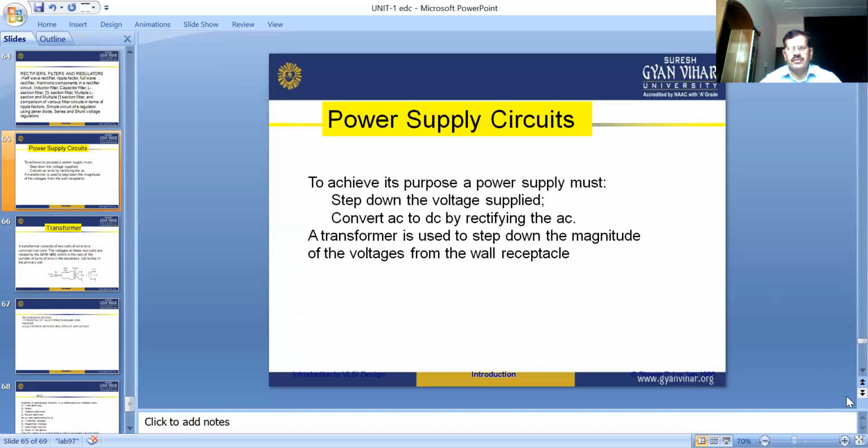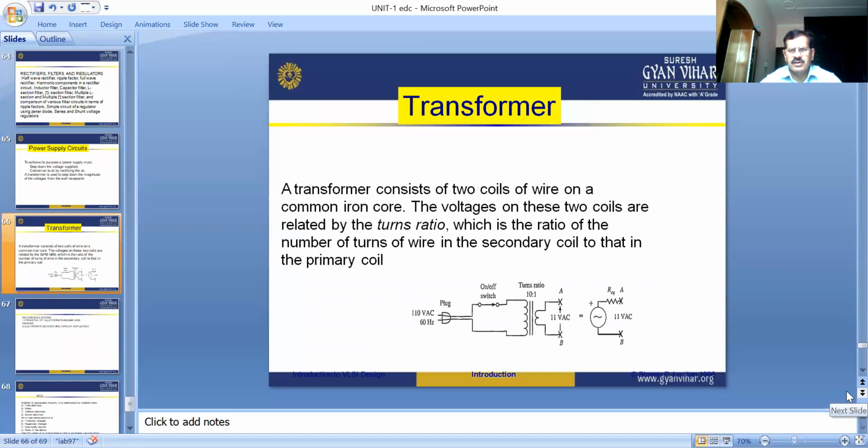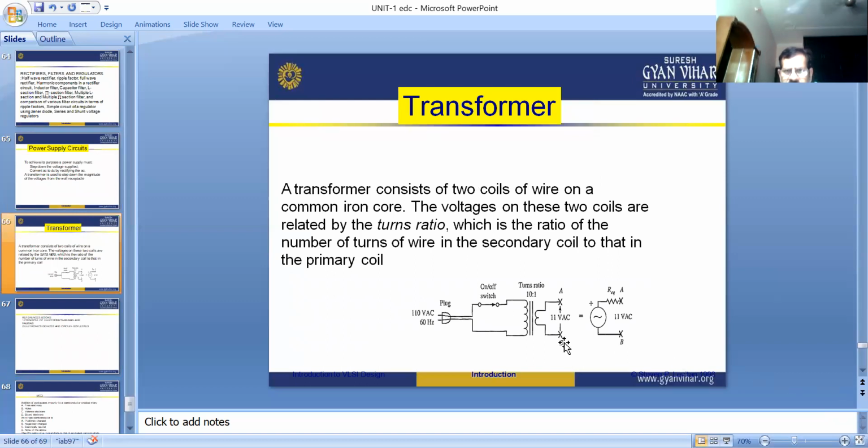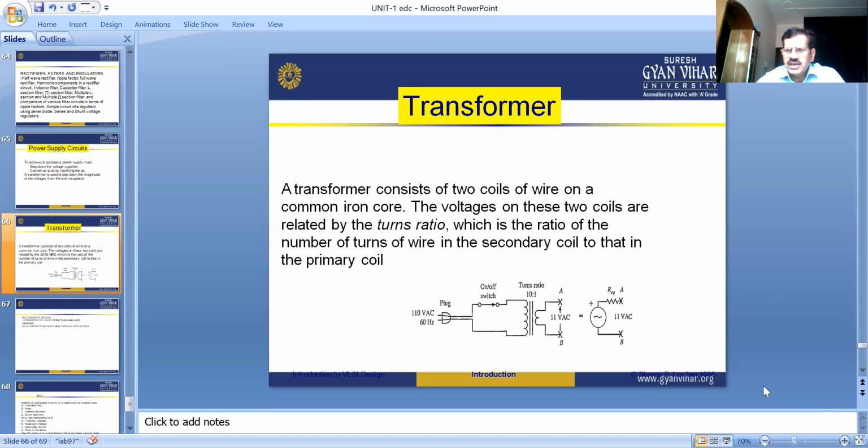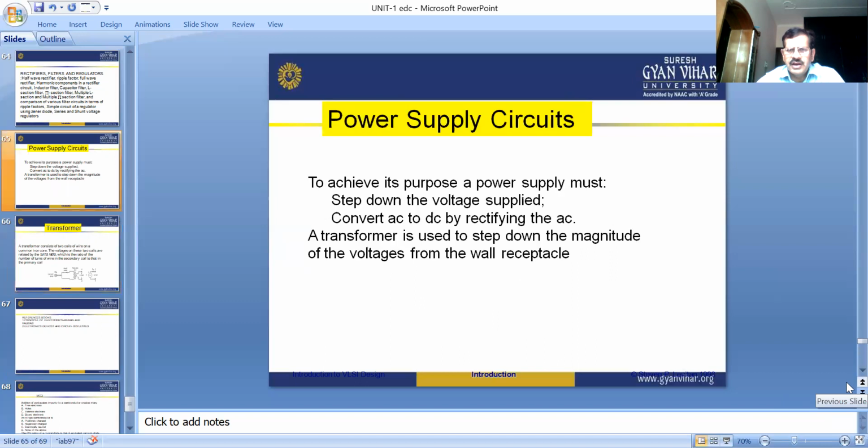because you see in this circuit we construct a rectifier circuit. So first of all, AC supply is applied to the transformer, and generally the transformer used is a step down type transformer. Basically transformers are of two types, step down and step up. For designing the rectifiers, we use the step down transformer.